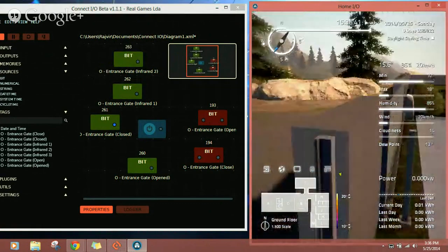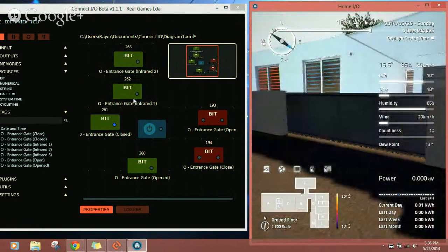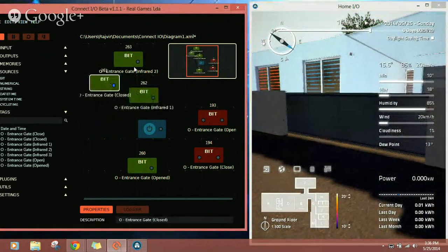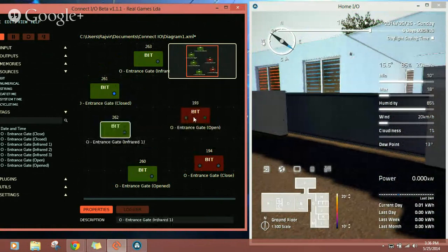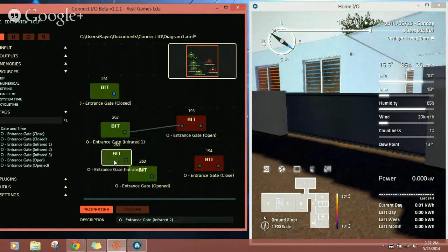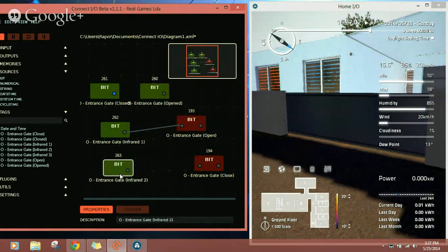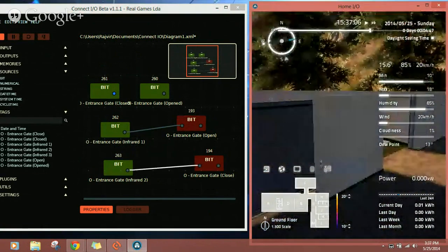So how should we automate that? Now, this is the logic. This is my sensor 1. If you are new to creating logics, what is the first thing that you'll do? You'll just click the sensor 1 and connect it to open. All right, and you will take infrared sensor 2 and make it close like that. Every immature programmer will do this. But this is not reliable.